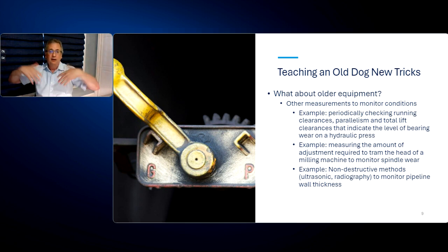These are out in the elements, and they had to stop the flow through the pipeline as soon as they cut that insulation out, and then they would do their checks. They did some research a few years ago and found, I think it's radiography type technology. They didn't have to cut out the insulation, so the pipeline could keep flowing with the contents, and they would get their accurate reading. So it was non-destructive at every level.